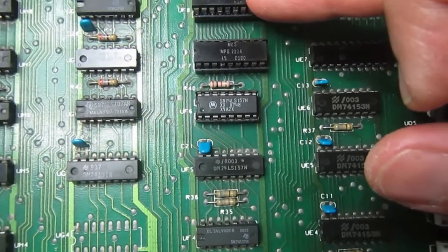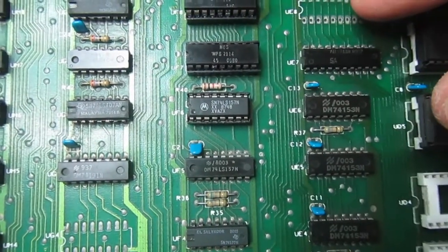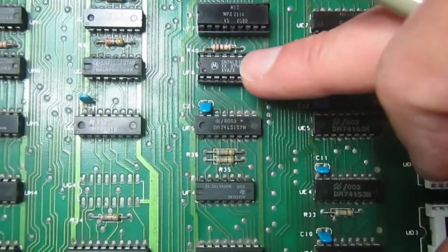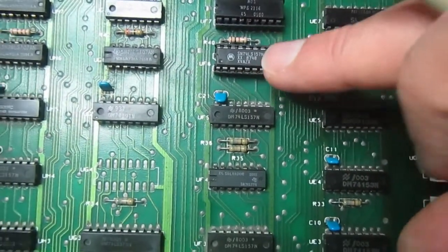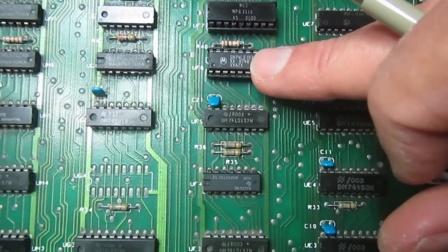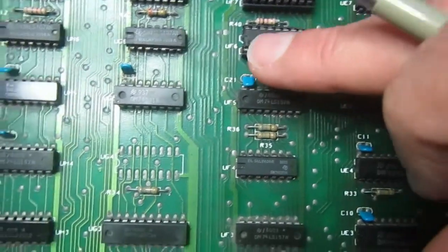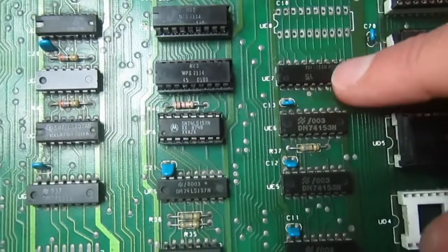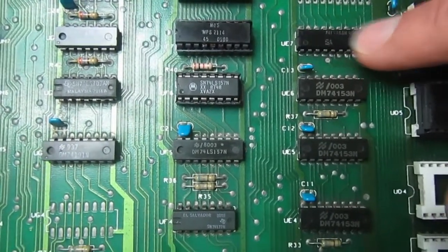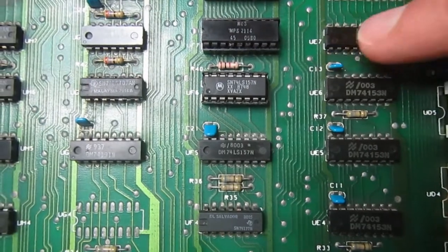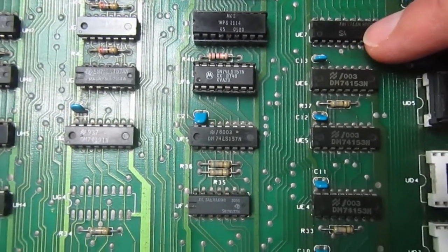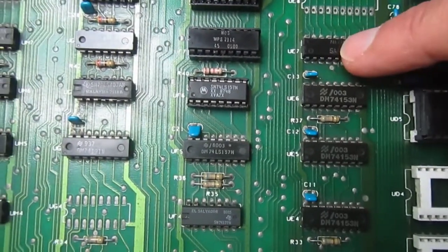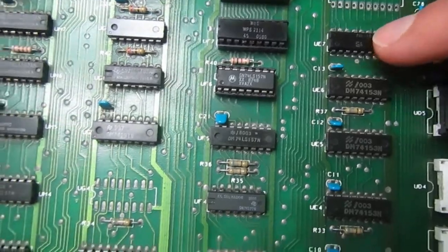and so I tried to remove the two video RAMs, and without these 244, that signal that looked bad was still looking bad with the original 74LS157 at UF6. And it was only driving the remaining 74LS244 at UE7, I mean. But I didn't find any current spike on pin 19 of this UE7, so I decided